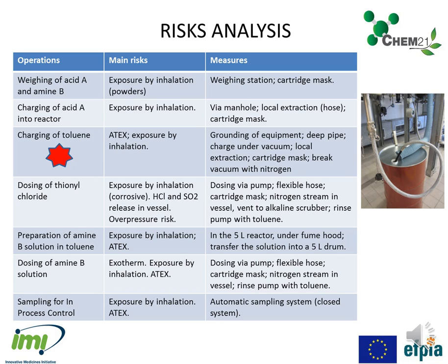The transfer from the lab to the kilolab or pilot plant must contain a risk analysis. The process is divided into elemental operations, and for each operation, the main risks are listed. It is often linked with ATEX or occupational health. Then, the safety measures are decided. Do not hesitate to give details.